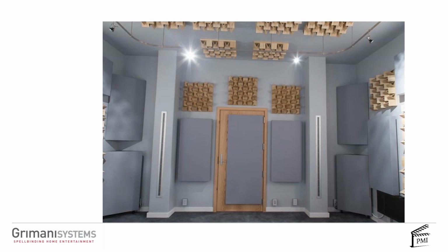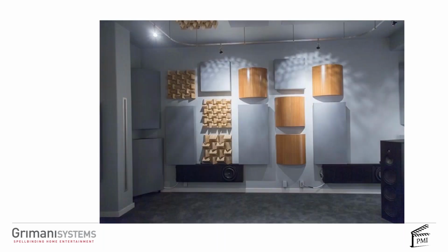That's a great question, and that's another hour conversation. Typically, by the time you have that 15% of absorption and 15% of diffusion, it is going to fill in the walls, like you see here. I know this looks like a lot of stuff, but if you took all of those absorbers and clustered them into the corner, it's not a big portion of it. This is probably a good picture. This zone right here is left open in this room. You'll notice they're generally oriented in the zone between the speaker and the back of the wall, and there are gaps of about 4 or 5 inches, maybe up to 6 inches, between the things.